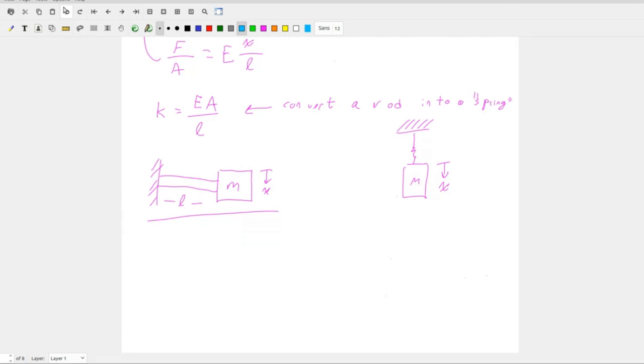There was one other question. Go ahead. So you have a horizontal system. No, we don't. We have a vertical system. Okay, so a vertical system, and yes, we're going to rotate it, but it should be fine because we can find the cross section A of the beams, right? And then we can divide that by length. So what we want to do here is get our K equivalent, right? What is the equivalent stiffness of this beam that gives us this spring? That makes sense? Okay. So we can do that.